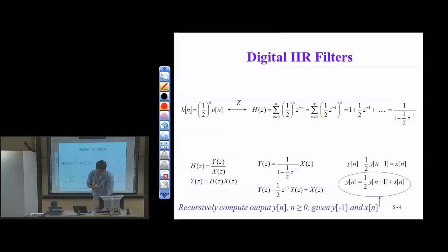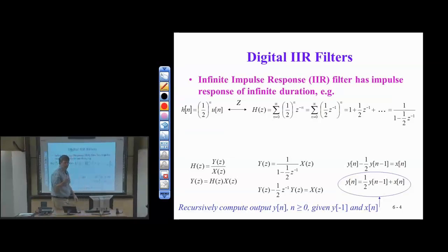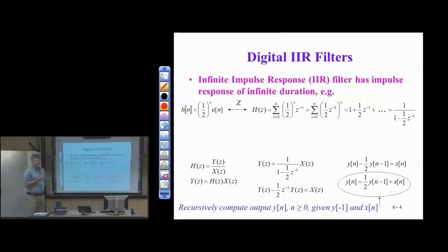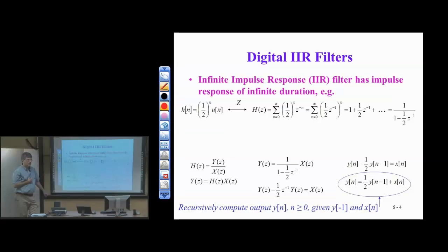Okay, so now let's move on. What I had on the previous slide was generally useful, whether we are going to have FIR or IIR filters. In fact, the 2 examples I had earlier, the 2-channel analysis, were FIR filters, and the audio example with the 3 channels of bandpass filters would probably be done as infinite impulse response filters in continuous-time analog, but could also be done as infinite impulse response filters in discrete-time and digital. So let's talk about infinite impulse response filters.